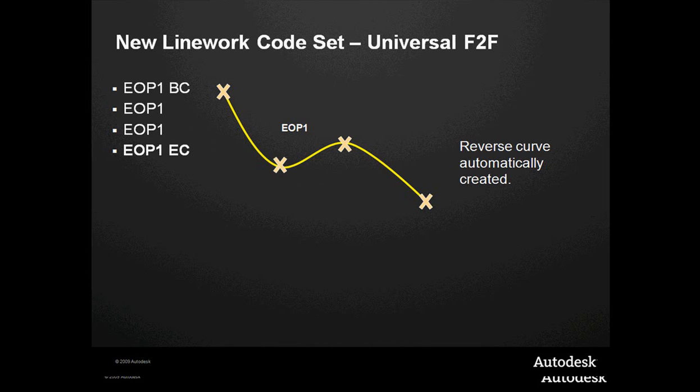What happens if you're surveying and you decide to go back and pick up another shot? Yeah, the question is, we finish, I get down here and then realize, I probably should pick up another one in the middle of here. What's going to happen is a couple different things. We have more flexibility than we had before, in that I don't have to go back and change it in the field book. I can change it in the drawing, and it will update the line work accordingly. When the information is processed, we can do it by point order, or we can do it by import order, but there will be some things that we'll manually have to fix. It will depend on the situation, but some things we can resolve automatically. In other situations, we have to resolve manually. Okay, but we don't have to go back into the field book and do it anymore.